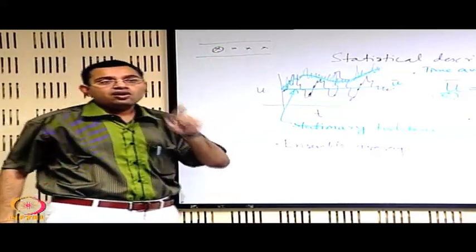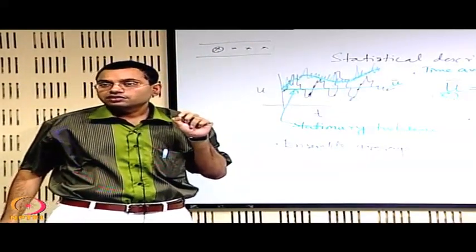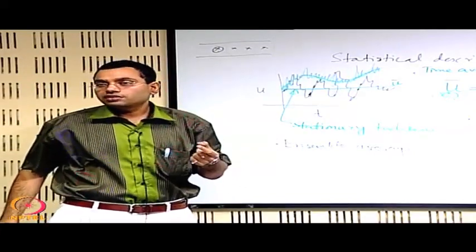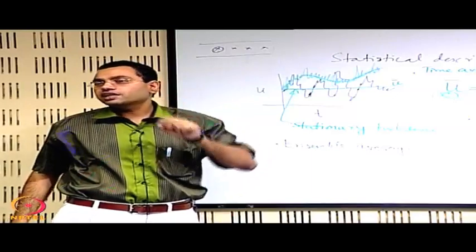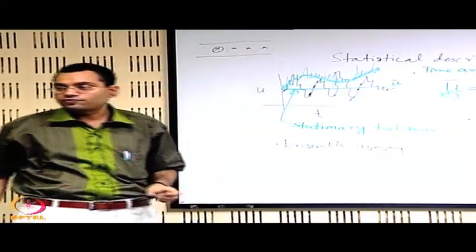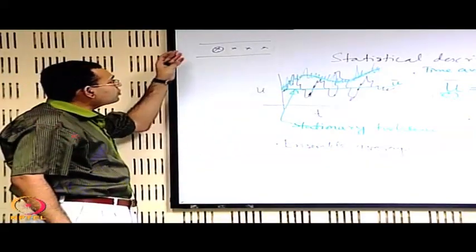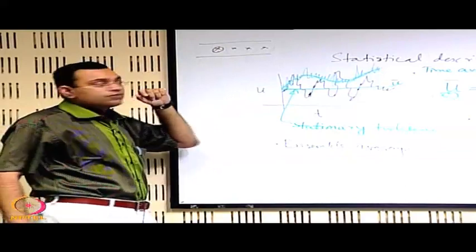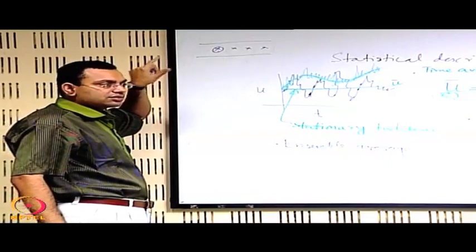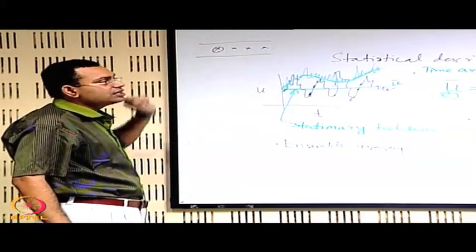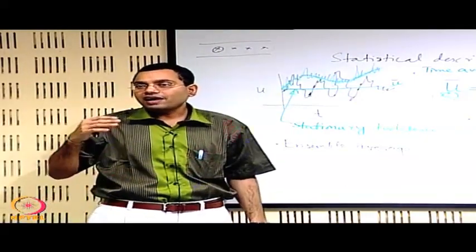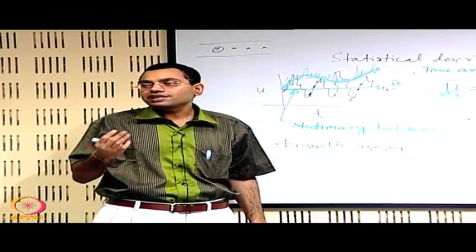These experiments are all done at identical conditions, but because of the randomness the output is not identical, because there could be slight variations in the experimental conditions and those got amplified, that is like an instability that is there in a turbulent flow. So, if you repeat such experiments, for each experiment you will get some data or information at your identified points at a given instant of time, and you can make an average prediction out of all experiments, and that average prediction out of all experiments is known as ensemble average.